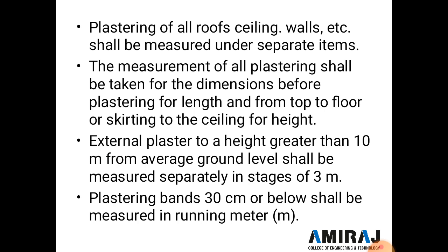The measurement of the plaster shall be taken from the dimensions before plastering, of length, and from top to floor, or skirting to the ceiling for height. External plaster to a height greater than 10 meter above average ground level shall be measured separately in stages of 3 meter, and plastering bands of 30 centimeter or below shall be measured as running meter.